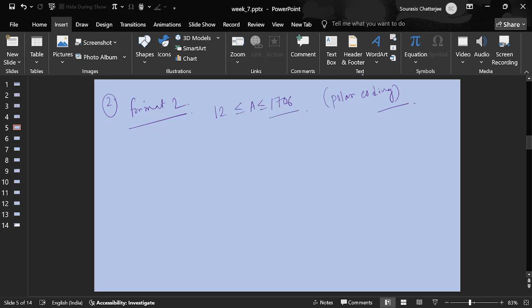Okay. And could that also be a reason? Let's say the user is observing very good SNR, or let's say it's a high priority user. So maybe I am allocating it the entire band for a particular slot, and there are multiple subbands, right? If we talk in terms of subcarriers or PRBs, I am basically estimating the channel for every PRB, considering a hypothetical situation, and feeding it back. So in that way it's also very high, right?